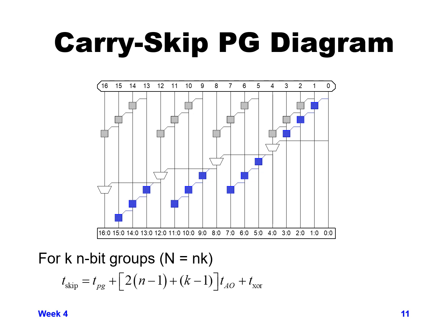And then we have k minus 1 AND OR functions that we're going through for the 3 white mux type boxes in the middle. So the total number of AND OR functions is k minus 1 plus n minus 1 times 2.